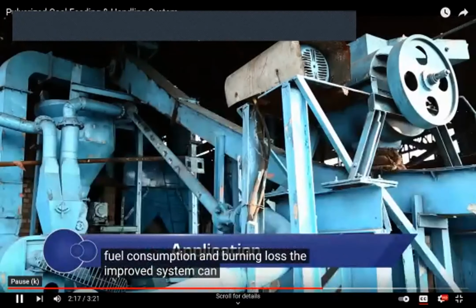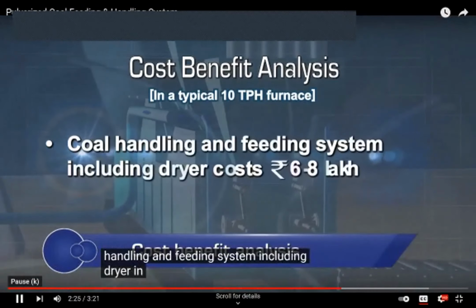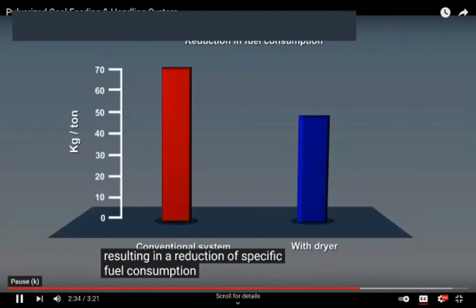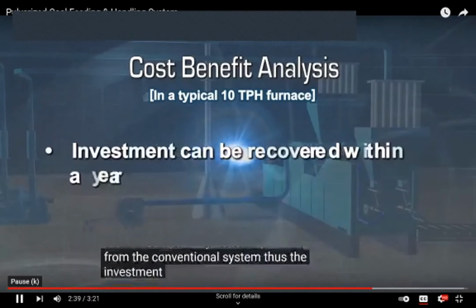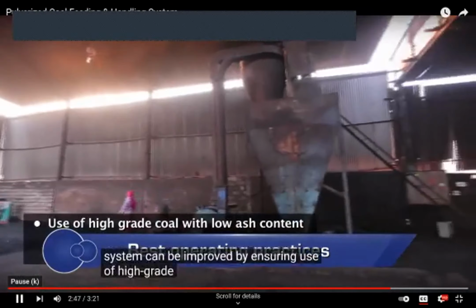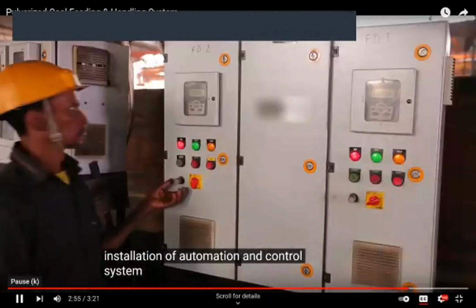The improved system can be used for any capacities of reheating furnace. The coal handling and feeding system, including dryer, in a typical 10 TPH furnace can cost around 6 to 8 lakh rupees, resulting in a reduction of specific fuel consumption by 20 to 40% from the conventional system. Thus, the investment made can be recovered within less than a year. The efficiency of the system can be improved by ensuring use of high-grade coal with low ash content, high-efficiency recuperator, and installation of automation and control system.